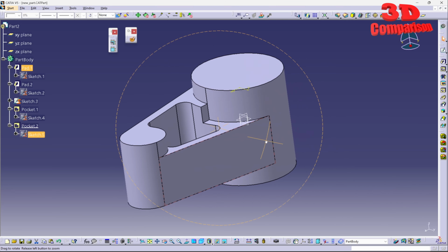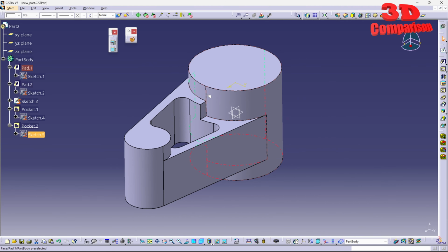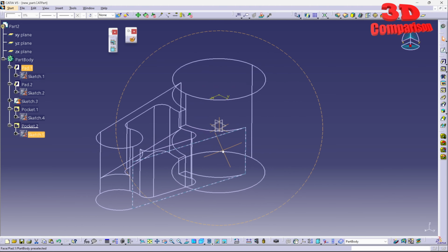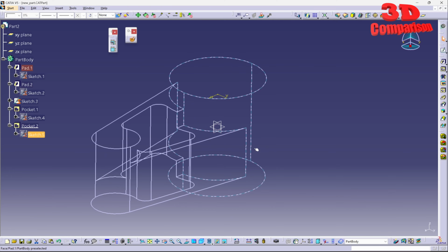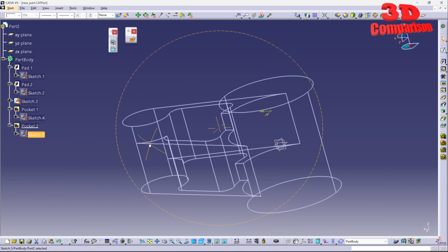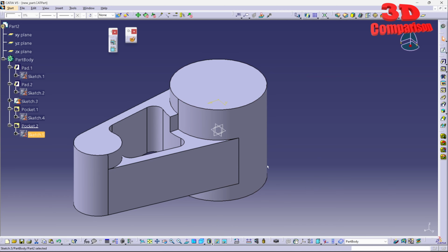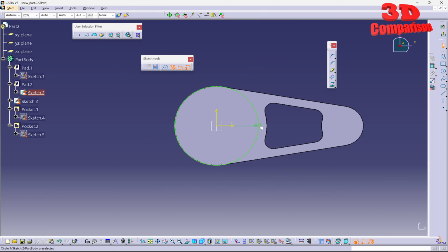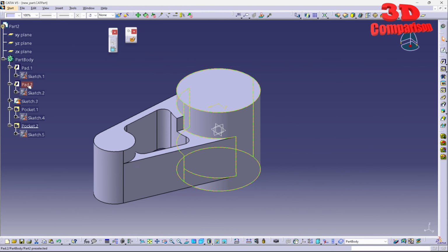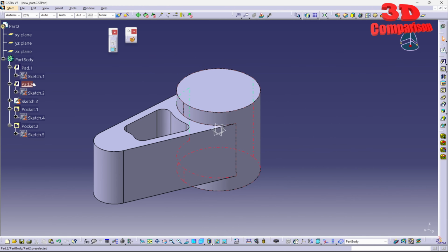And this is the main problem within CATIA, that extruded circles will have those wireframe added elements. As you can see within wireframe, we have the top circle, the bottom one, and we have those two lines. And if I rotate around the viewport, those will always remain within that section. Even if I go over here onto this circle and define this as the work object, so we only have the second pad over here.